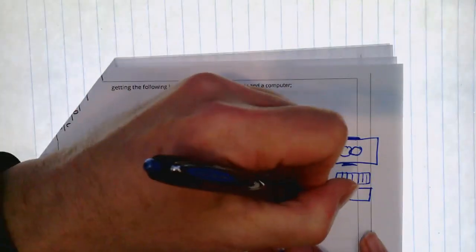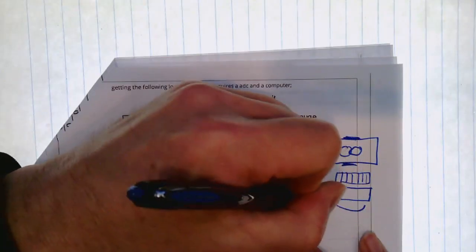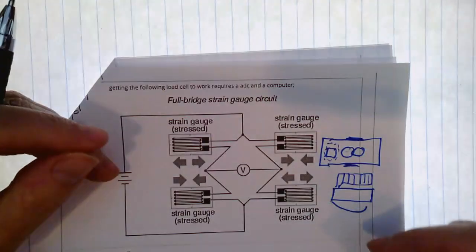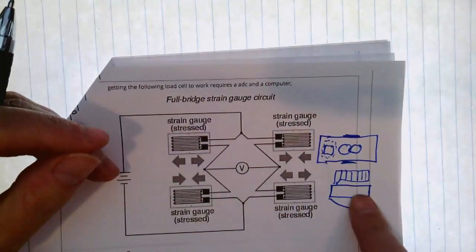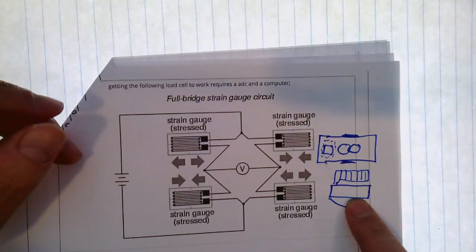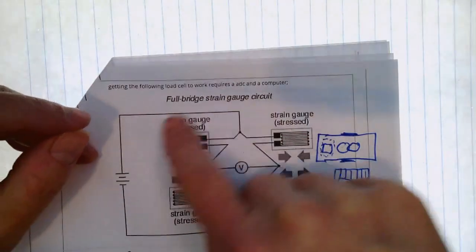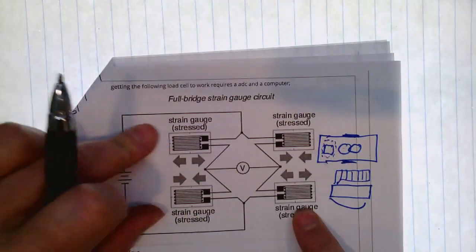And eventually you'll have what's called engineering creep. These things will start to bend and bow, especially if they're particle board, until eventually they break. If you instrument them with these strain gauges, you'll tell how much they're bending. And that's the key. So this is a strain gauge arrangement in a thing called a Wheatstone bridge.